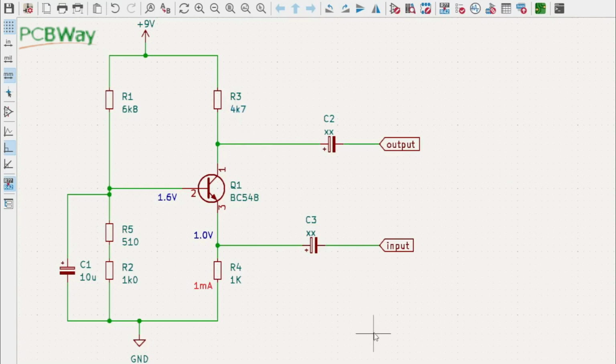And just to round off the AC decoupling for the input and the output, we'll use 4.7 microfarad capacitors, as I've used them before and they're already on my little PCBs. So we'll stick with them. They'll affect the bandwidth a bit at the low frequency end, but just for the experiment I'm not really worried about that. Now we have the circuit design, let's build the kit with a little background music.